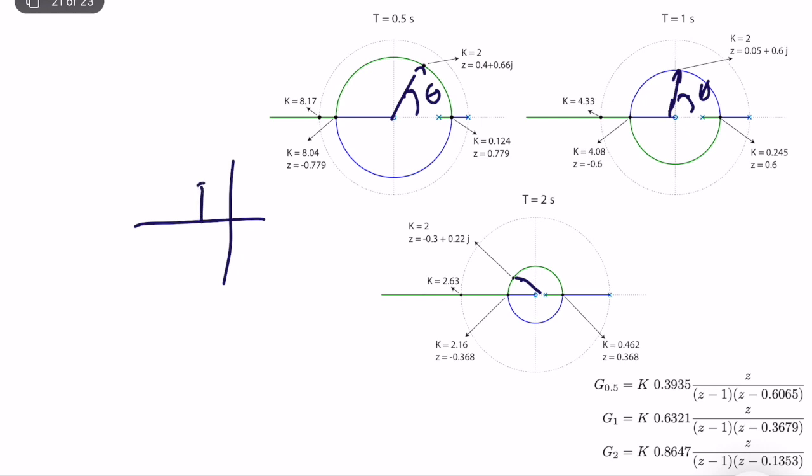And if you remember, if you diverge from the real line, you increase the overshoot and you decrease the damping, it's the same thing. If you just map this line to the complex plane, it will be a circle inside the unit circle, and when you deviate from this, you will approach the negative real line, where the oscillations will be very extreme.